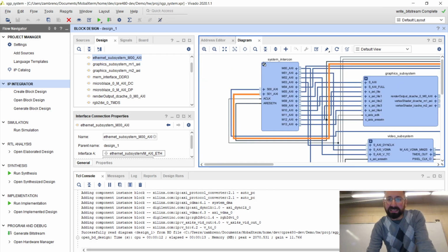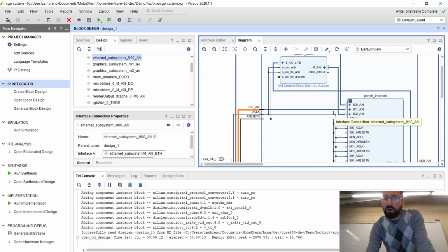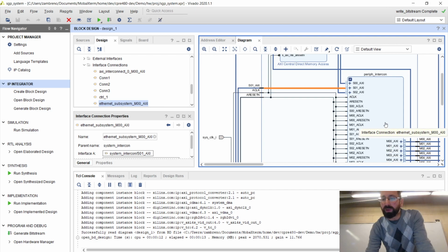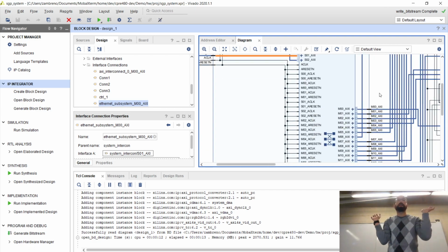That's connecting as a sort of a sender port on this interconnection. Ultimately, it's going into a switch, which we will also talk about, and then potentially connecting to the whole rest of the design. So you can think of that as a bus switch or like a router. It's saying from that Ethernet core that's there, generate the correct set of AXI signals and then send it off to the rest of your design. That is what our driver then has to interface with.